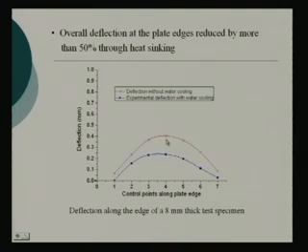You can see there is a substantial drop in the distortion level. In this case it was around 0.4 millimeter deflection, here it was roughly 0.2 millimeter deflection. The deflection values are very small, but that is not important, because that will depend on what thickness of plate, how much heat input, and what the deformation level is. Overall there is a 50% reduction in distortion.